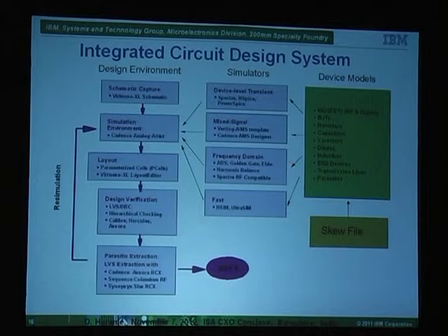So it's the quality of these. Digital, it's off or it's on. RF analog and mixed signal, what counts is the quality of the model that you now have to trace the entire curve of operation and derivatives. All the derivatives in the model have to be continuous. So this has really differentiated us, and the Bangalore team has done an incredible job at doing these compact models. Now, the SKU file means we take all the statistical aspects of the fab.